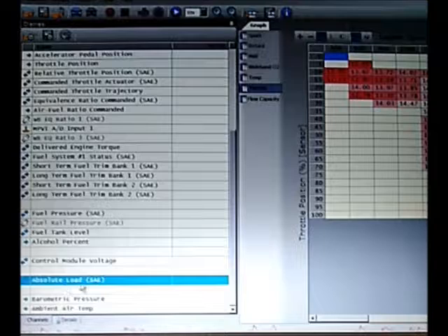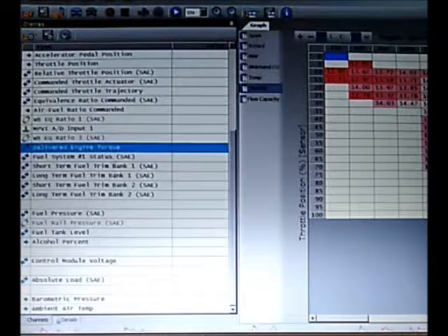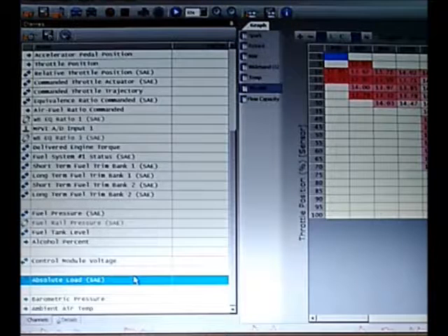The absolute load is a similar type of quantity to delivered engine torque. Both measure load on the car. And essentially, if there's less than 0 load on the car, it means that the car is decelerating. So you can use either of these parameters, whichever one works for you. This one's SAE, so I think it has to work. So maybe this is the one that I actually used. But setting that greater than 0 will help you keep that decel data out of your scan.